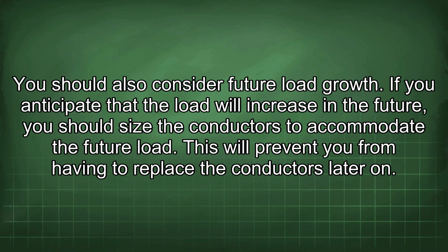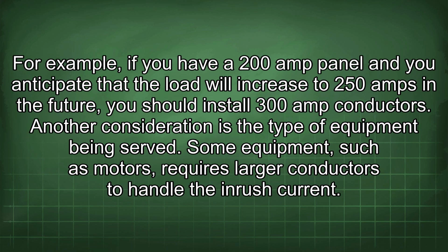You should also consider future load growth. If you anticipate that the load will increase in the future, you should size the conductors to accommodate the future load. This will prevent you from having to replace the conductors later on. For example, if you have a 200 amp panel and you anticipate that the load will increase to 250 amps in the future, you should install 300 amp conductors.